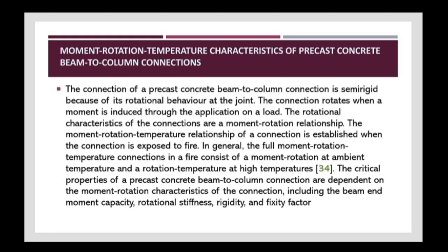The moment rotation temperature relationship of a connection is established when the connection is exposed to fire. In general, the full moment rotation temperature curve of connections in fire consists of the moment rotation at the ambient temperature and the moment rotation at high temperature. The critical properties of precast concrete beam to column connection depend on the moment rotation characteristics of connections, including the beam and moment capacity, rotational stiffness, rigidity, and fixity factor.